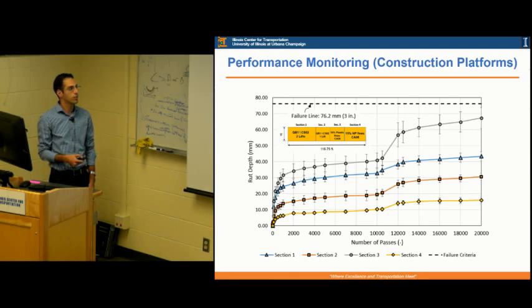And if you look particularly at this point here, where you have the increase in slope, this is where we got a lot of rain while we were testing, and Atlas was running at that point. So in these points here, between 10,000 and 10,500, there was a little bit of rain, but the machine was stopping, so there was no loading of the pavement. But in these points here, we had loading of the pavement plus rain, and that accelerated the accumulation of rutting